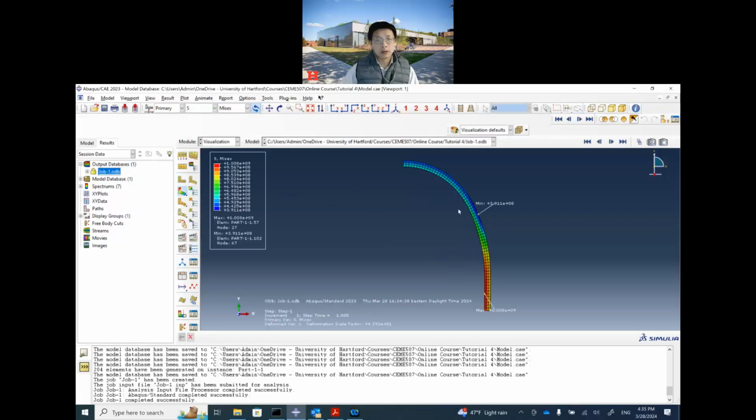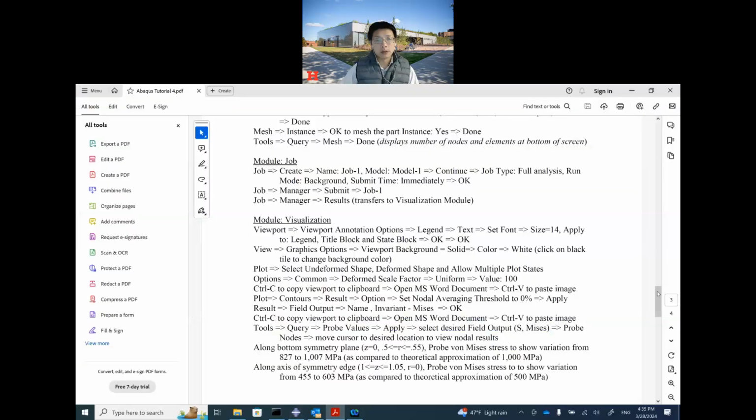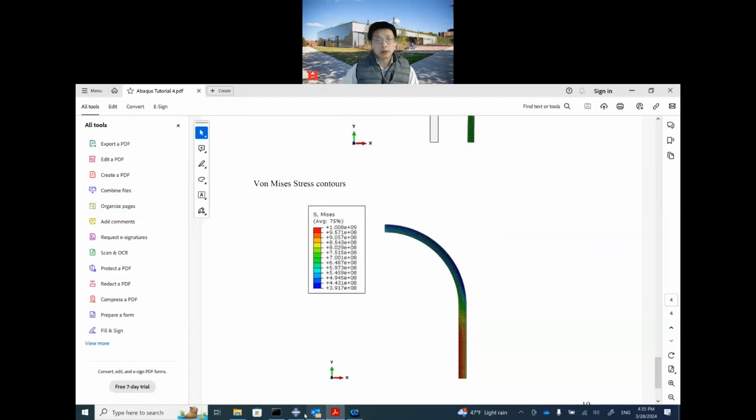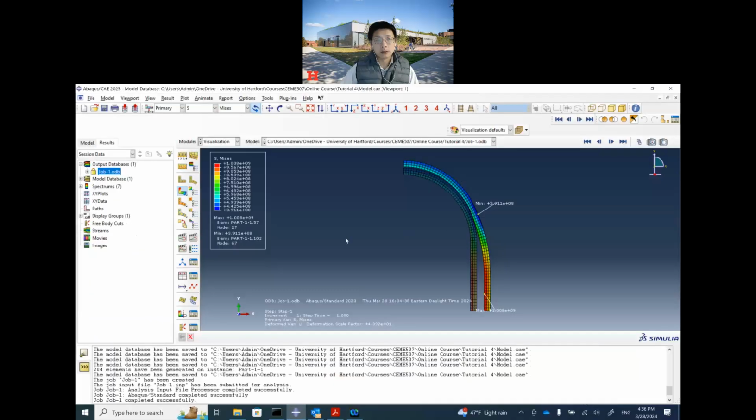Show the stress. So when we say stress, we can also show the stresses on deformed and undeformed shape. The maximum value is given. That's in Pascal. The largest is about 1.9 gigapascal. We can compare the results. It's shown here. And this is the average. You can show the average. So this is the vertices, stresses. You can also show the stresses along some lines here. And so there is a tool.